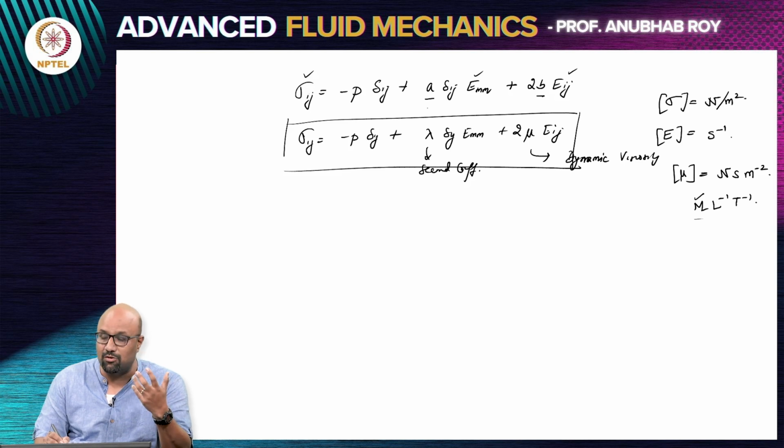So, what assumptions have you made? The first thing that you have assumed is that there is a linear response in the system. There is a linear material in terms of its constitutive relation. Now, how do you validate this? One obvious validation, which is how these theories have developed, is from experiments. You perform experiments and you try to see what kind of a stress the system develops, given that you apply some kind of a velocity gradient or some kind of a straining in the problem.